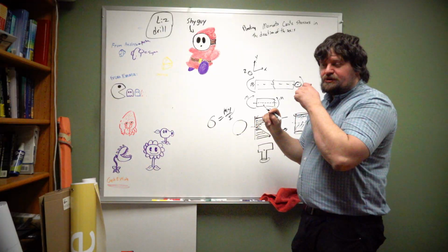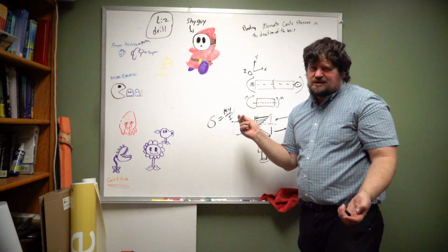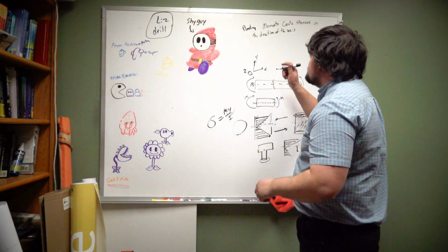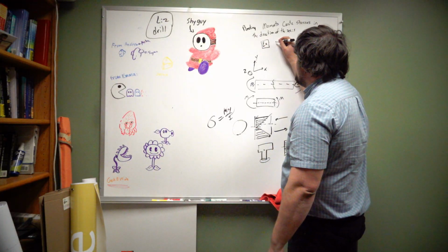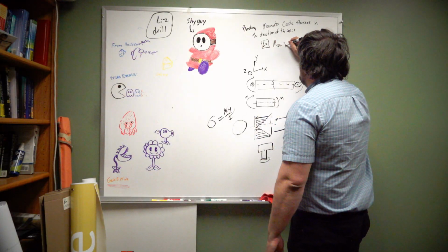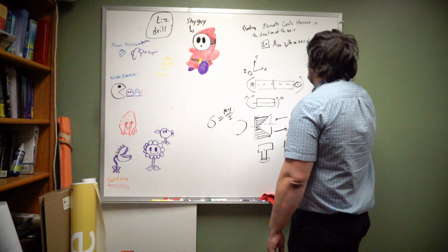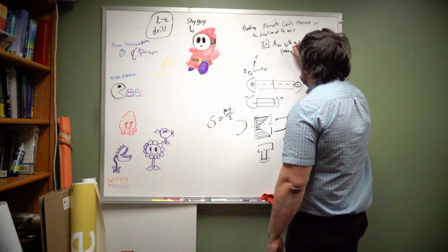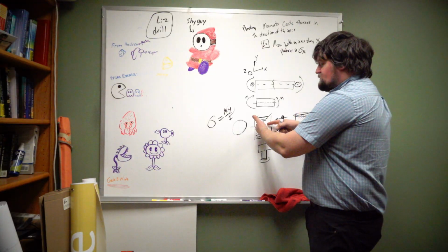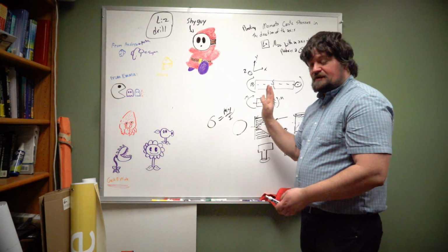Yes, that is true, but those shear loads are much smaller in scale than the bending loads themselves, so we don't usually consider them. We focus mostly on the bending loads. Okay, so for example, if I apply an Mzz moment, this with an axis along x produces a sigma x stress. Okay, so here what we would see is all of these are sigma x's. Okay, and so that's the bending moment.